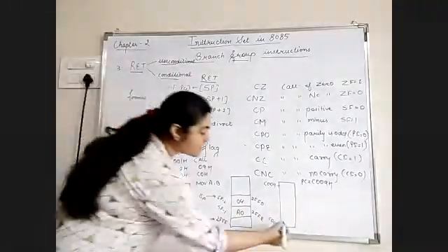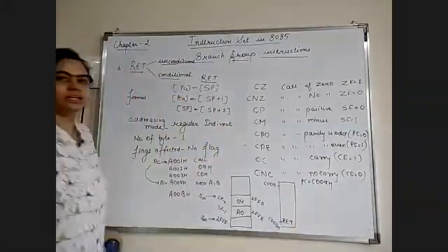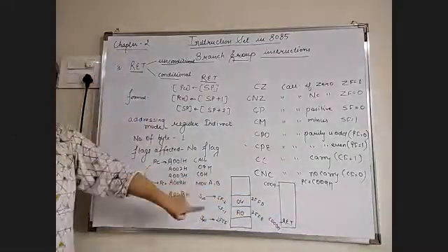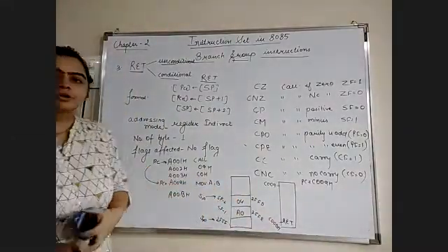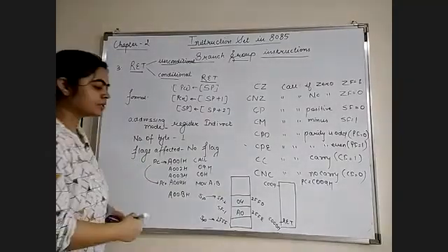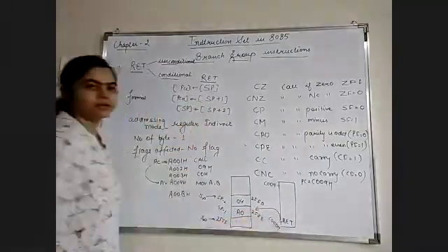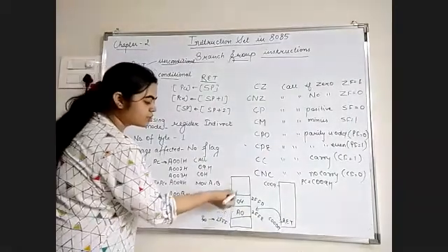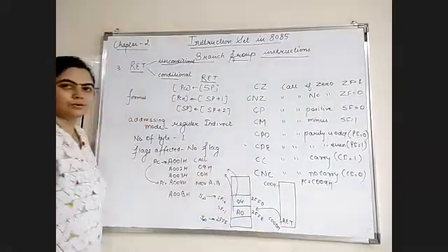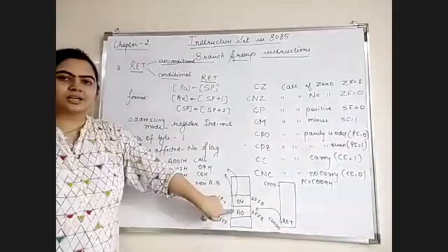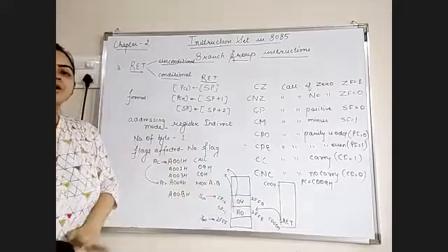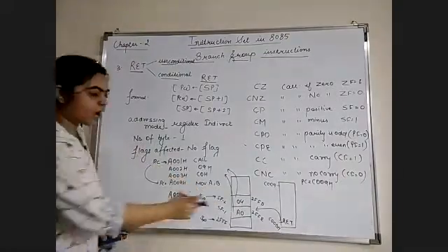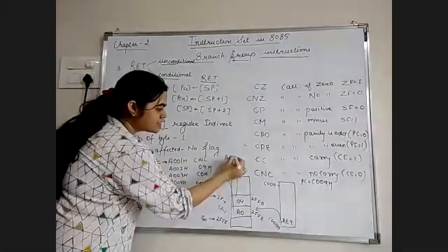Now suppose at this location we have an instruction RET. Once this instruction is fetched, decoded and executed by the microprocessor, the microprocessor jumps to the stack memory and reads the content. It will read 04 and it will read A0. After loading these contents into the program counter, it will be A004H.